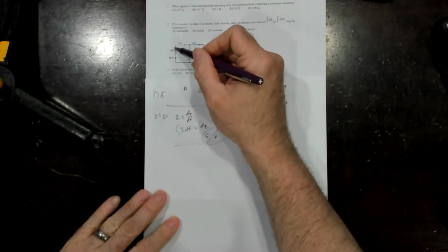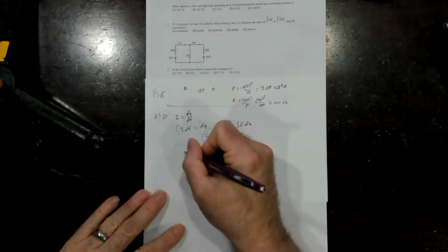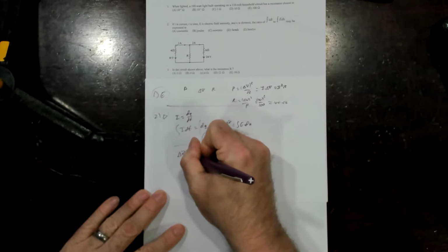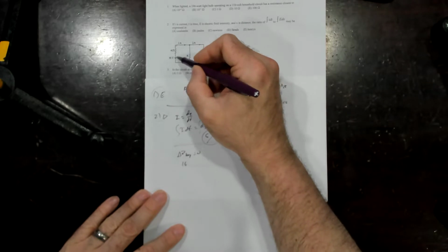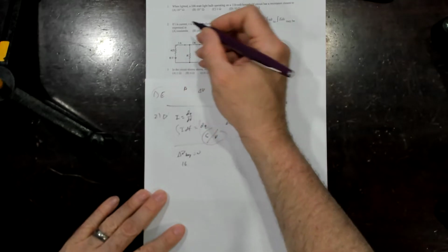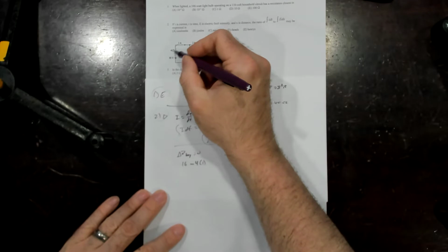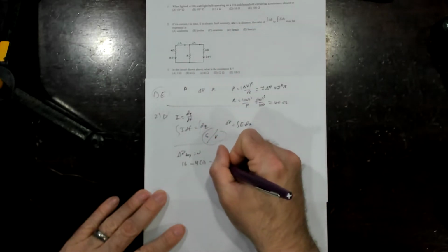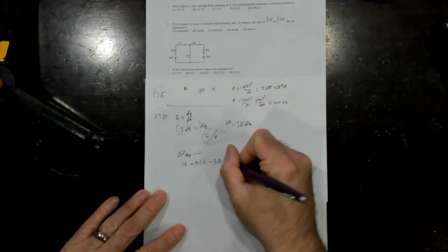So I'm going to do a loop law on this left loop, starting at the low side of the battery, going around clockwise. First I'm going to go up 16 volts from the low V to high V side of the battery, since my delta V around the loop is 0. If I have 1 amp flowing here, I've got 1 amp flowing through all this. So 1 amp through 4 ohms, I'm going with the current, so I go down 4 times 1, I times R. And then I'm going to go down 3 amps through R ohms, and then I'm back to the start, so that adds to 0.